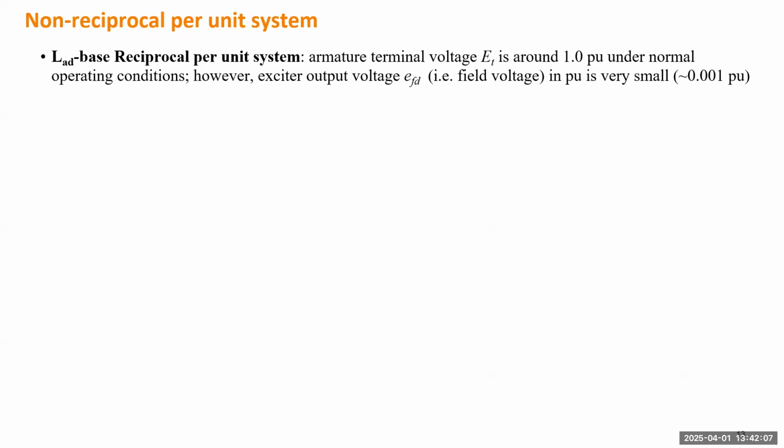Okay, so next we need to explain one thing. We left this question from the generator modeling session. If you remember, there was one very busy slide, where we start from a flux linkage equation and voltage equation, and gradually derive a set of differential equations, using only the time constants and the single prime and double prime quantities.